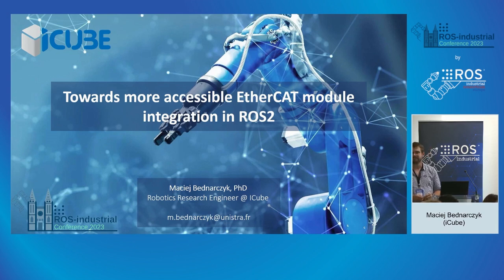Thank you very much. As a user of both ROS2 control and the EtherCAT driver, thank you for the work you've done there. And if this gets too technical, we can take it offline for lunch. But what I'm wondering is about the architecture that you have with the slaves: the slaves are part of the component. So for one joint, you have an EtherCAT slave. For one sensor, you have an EtherCAT slave.